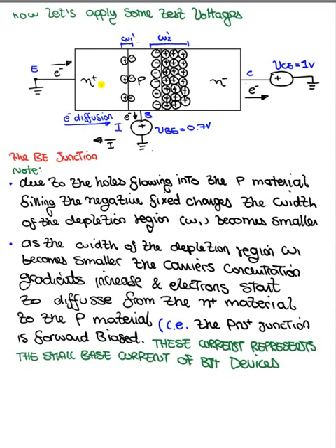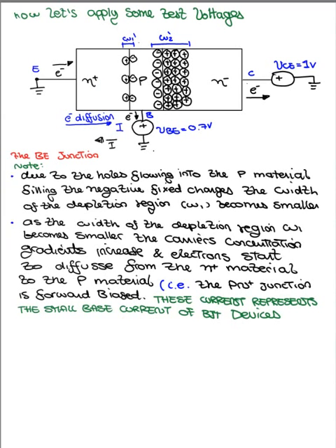Okay, but now there is something that we have to take into account. There is a huge point that we have to consider, and it is that the size of the P material and the doping is very small compared to the N plus material. So the number of holes in the P material is a lot smaller than the number of electrons in the N plus material. What that means is that a lot of electrons are coming to the P material but have no hole to fill.